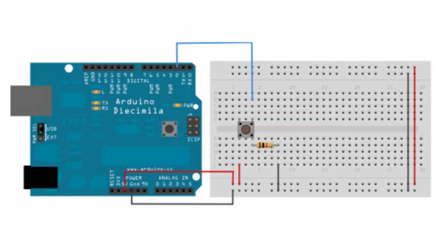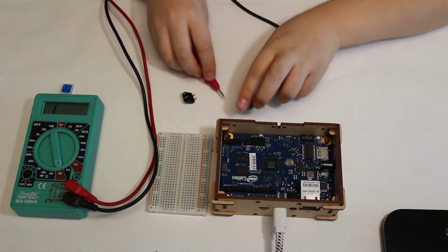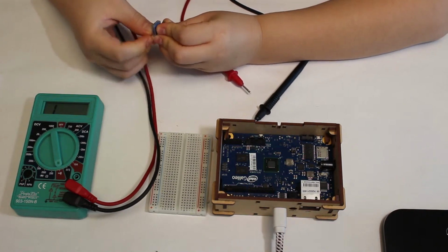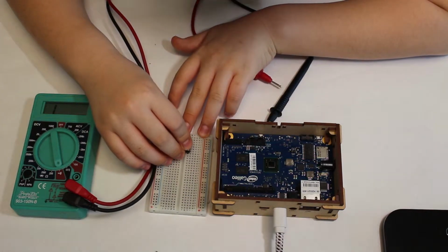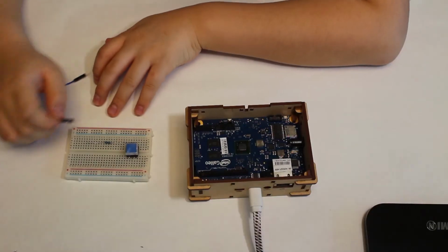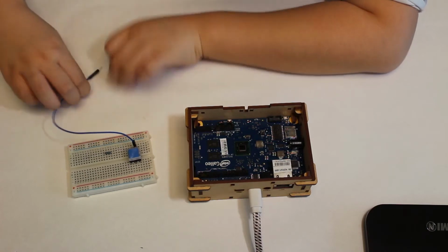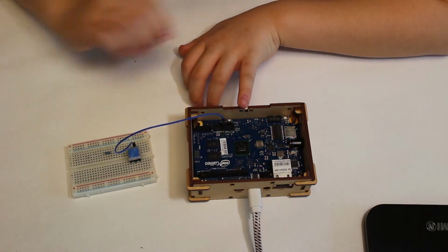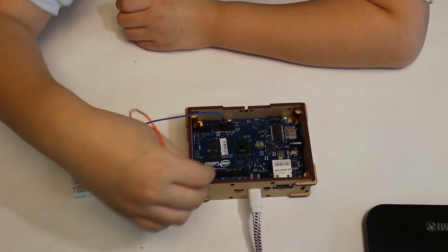In the case of a push button, you should be aware that two pins are connected together as a pair. Of the pins that are not connected to each other, connect one to Galileo's 5V using a jumper wire. The other pin needs to connect two ways at the same time. First, connect to Galileo's digital pin number 2 using another jumper wire. Next, connect to Galileo's GND through a 1K ohm resistor.